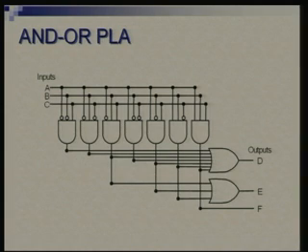Okay. So in general, you can form product terms which are of less than M inputs also. Okay. So some of these may not be connected, right, and therefore a PLA just needs to form enough number of terms so that all your outputs can be realized, and then you have a row of OR gates which will pick up necessary required subsets of these product terms and sum them.